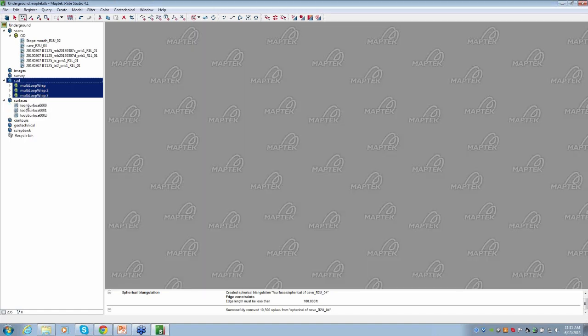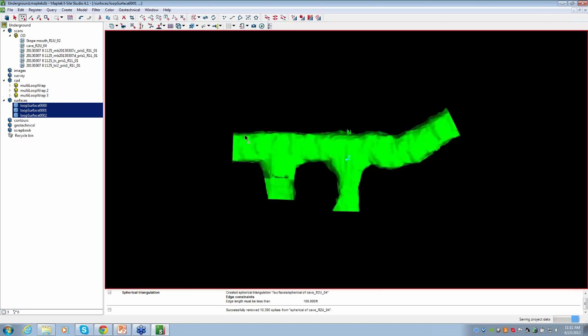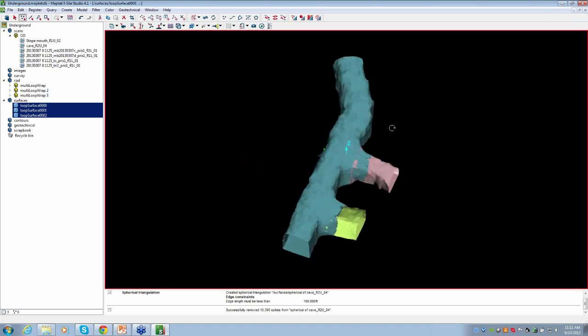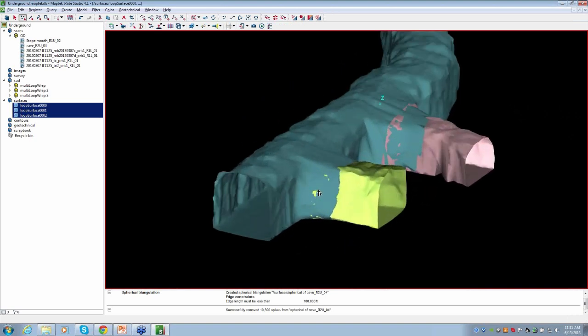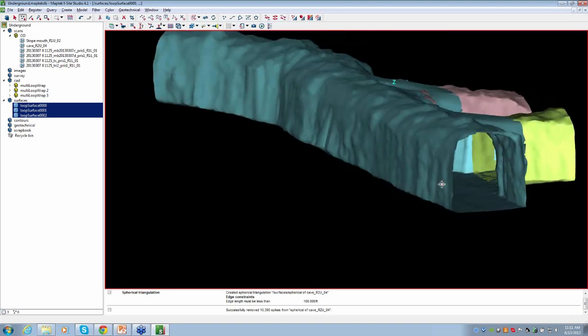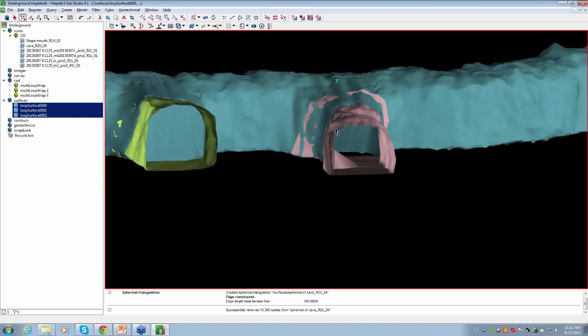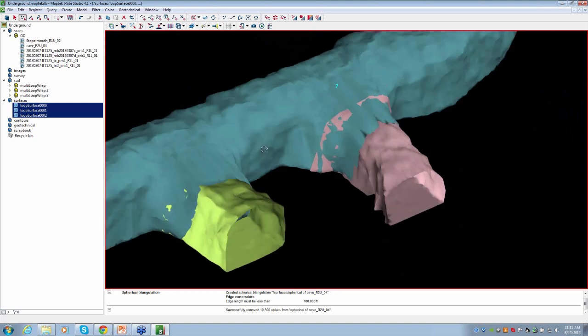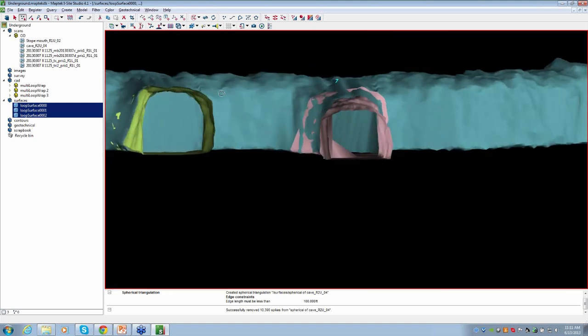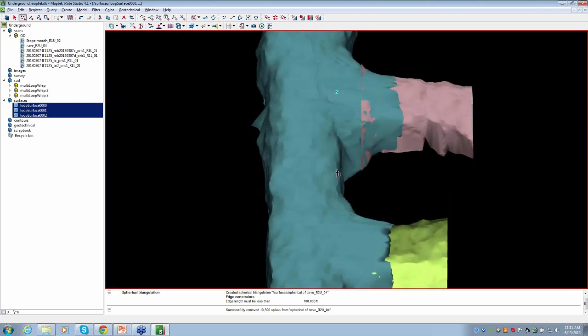And now I'm going to bring those surfaces in. So it goes ahead and it creates a separate triangulation for each one of those multi-loop wrap containers. And let's bring those into the viewer, see what those look like. I'm going to color those separately so you can easily see what we've got going on. So, and let's zoom in here. Check this out. So you can see there's ends on this blue one because I allowed it to go past the intersection, and that is absolutely not what it looks like. That's hideous. We want to get rid of that right away.